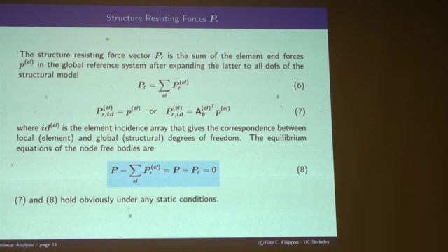And so here I want to show you some stuff that is specific to OpenSees, that in my view is the strength of OpenSees, but you don't find in too many other packages around the world. All right, so let's talk about it. The first part is trivial. Basically, this is undergraduate matrix analysis, right? The total resisting force vector is the sum of the element resisting forces.